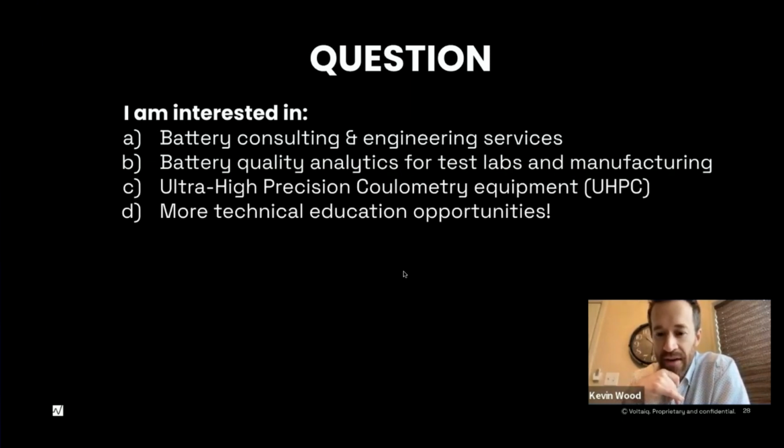More questions about DQDV, peak shifts, and aging mechanisms. I'm curious to maybe get your take, Stephen, on if you have any more advice on that. But a lot of times peak shifts are over potential driven. They can be new phases or like lithium going into new phases, but a lot of times peak shifts are over potential driven due to kinetics and transport limitations and buildup. And then peak intensity losses and changes can tell you where in specific phases you're losing lithium from, or maybe gaining lithium to, right, in some cases. So looking at all those things can be helpful.